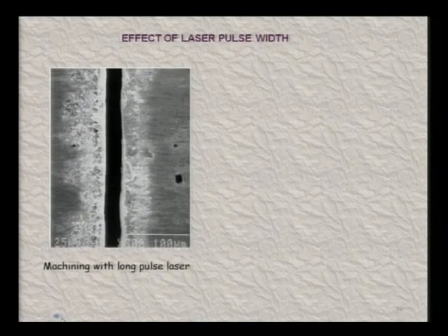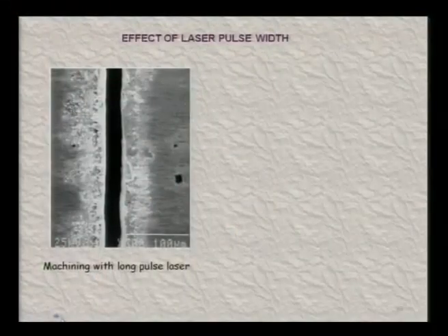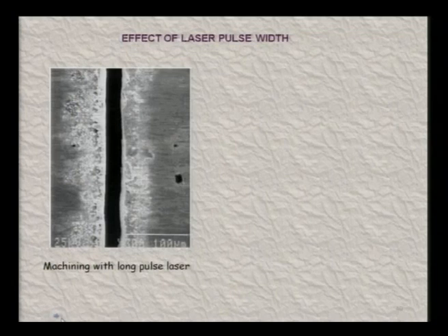Now, effects of laser pulse width. I have told you long pulses and short pulses both affect the quality of the machined component. Here I am going to show the effect of pulse width. Machining with a long pulse laser, you can see the irregularities, however small they may be. Although these are very fine, very small irregularities, as far as micro machining or micro parts are concerned, still irregularity is there when you are using the long pulse laser.